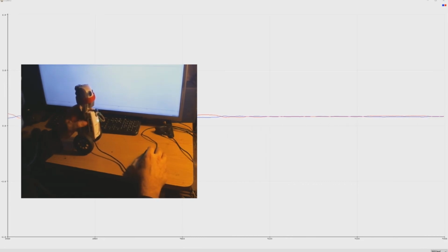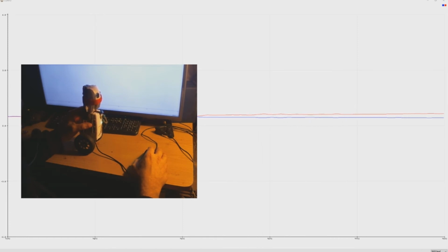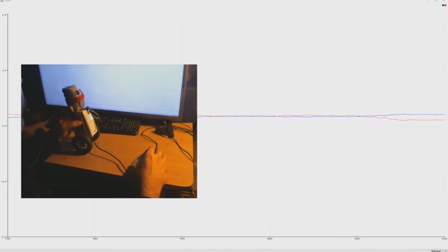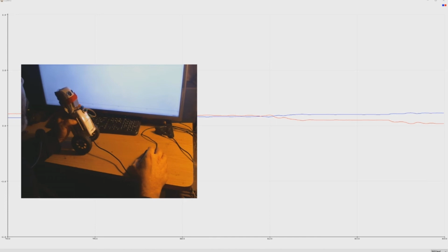Alright, right now I'm holding him on his balance point. And the graph is looking pretty good. Tip it just a little bit and that number goes up to react pretty well. It's getting there. It's a little bit jerky still. You tip it back and it should gradually keep increasing.